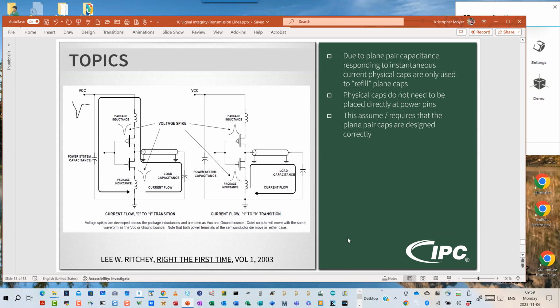No. Aging is typically an environmental related effect, such as humidity, temperature, and other things. Typically, capacitors are designed for switching. They're designed to store charge. So I've never heard of any situation where lots and lots of switching is causing the capacitor to age. That's usually just time related.